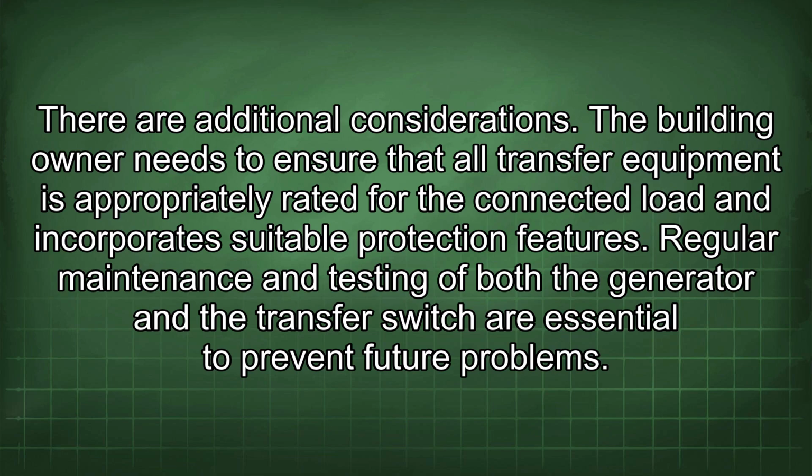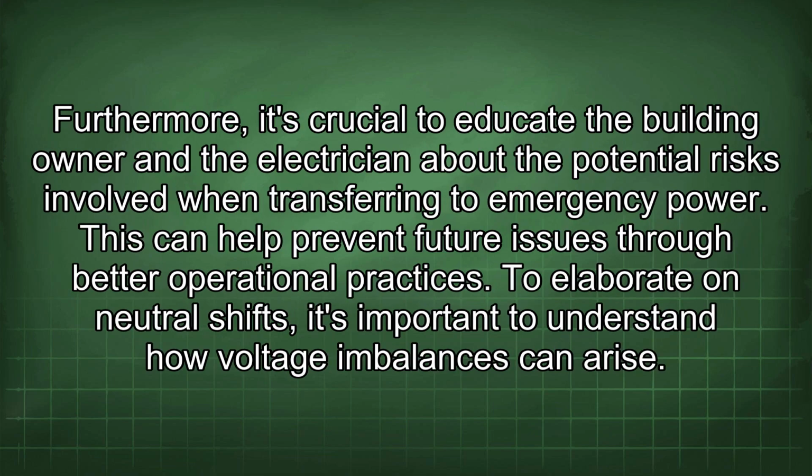There are additional considerations. The building owner needs to ensure that all transfer equipment is appropriately rated for the connected load and incorporate suitable protection features. Regular maintenance and testing of both the generator and the transfer switch are essential to prevent future problems. Furthermore, it's crucial to educate the building owner and the electrician about the potential risks involved when transferring to emergency power. This can help prevent future issues through better operational practices.